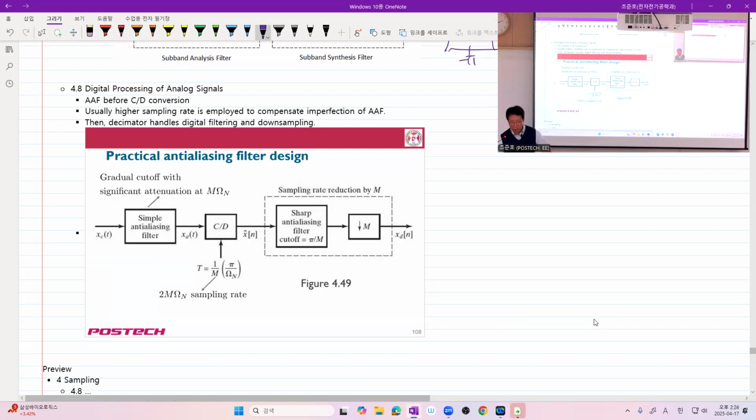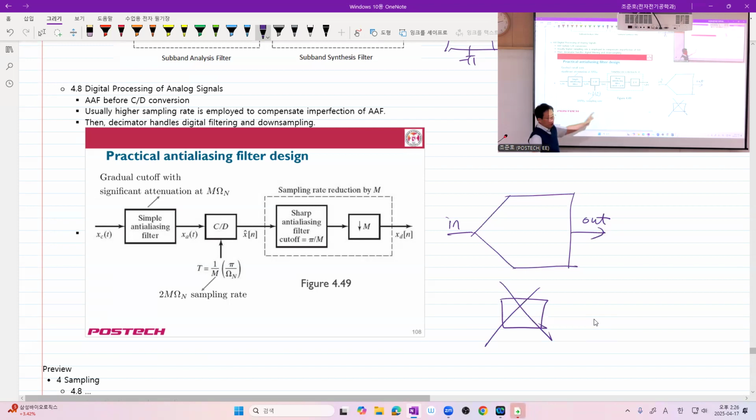And usually they have something like this. Probably I've drawn this block diagram there. It's not like a square, okay? They use some symbol like this. Here is the input and there is the output. The input part is a little bit triangular, or you may say it looks like a baseball home plate. Anyway, this part means analog, and that means digital, got it? Sometimes you may have a flipped version, but it's okay. This part is analog. Analog in and digital out.